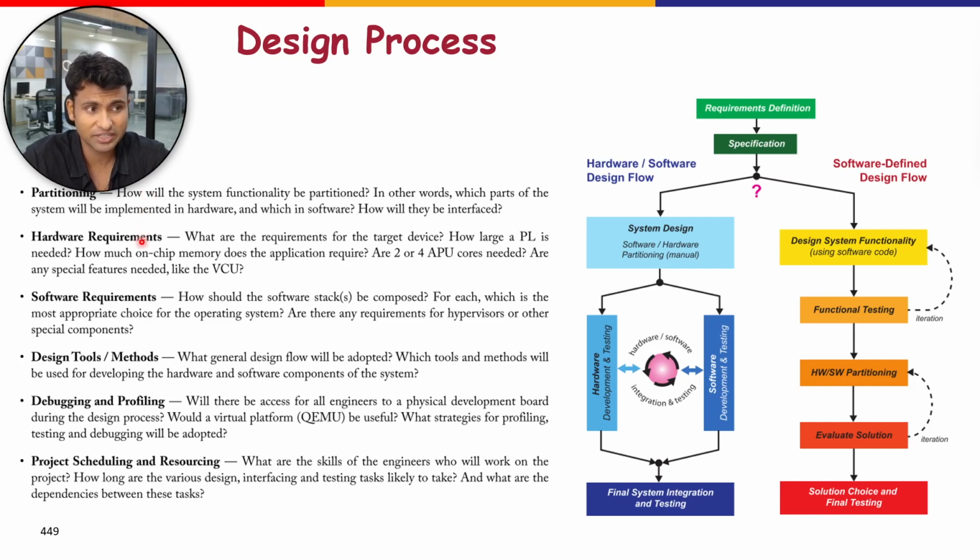Then come the hardware requirements. So what are the requirements for the target device? How large a PL is needed? How much on-chip memory does the application require? Are 2 APUs needed or 4? Are 2 cores needed or 4 cores inside the APU? Are there any special features needed, like the VCU in the PL?